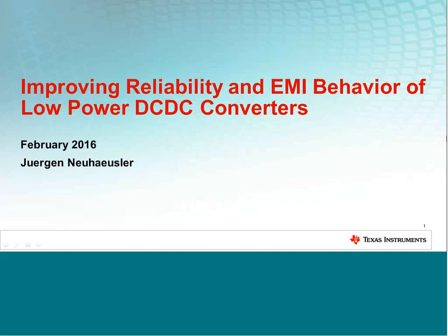Okay, welcome everybody to this webinar session, and especially to the second session, which is about improving reliability and EMI behavior of low-power DC-DC converters. Low-power DC-DC converters are typically very simple circuits, so all silicon or active circuitry is integrated in an IC, and they only use a few external components, typically input capacitors, inductors, and output capacitors.